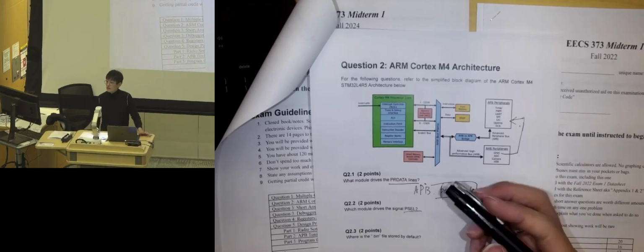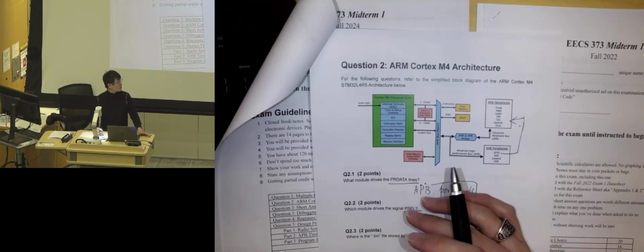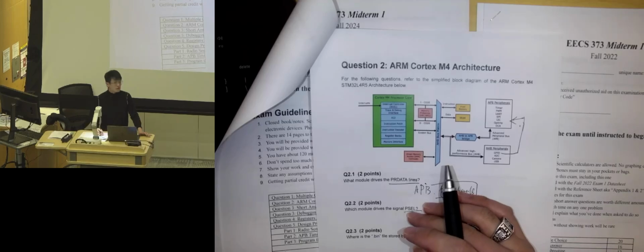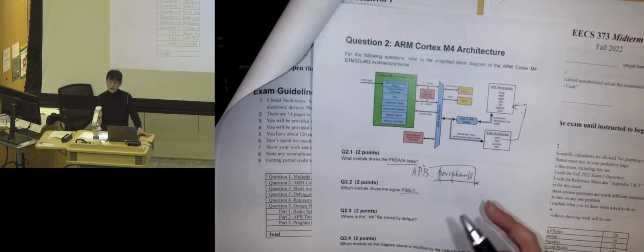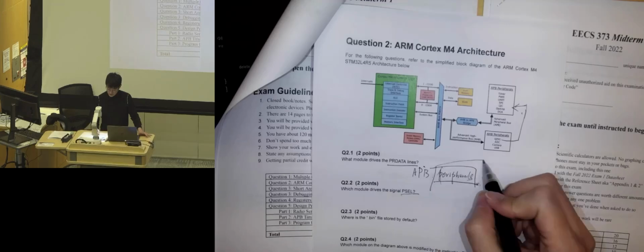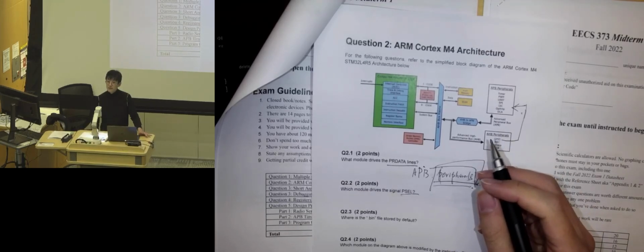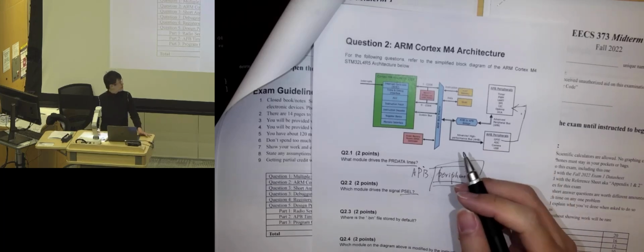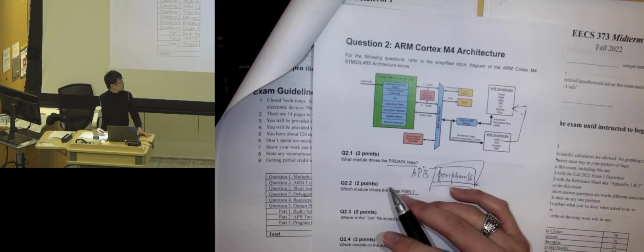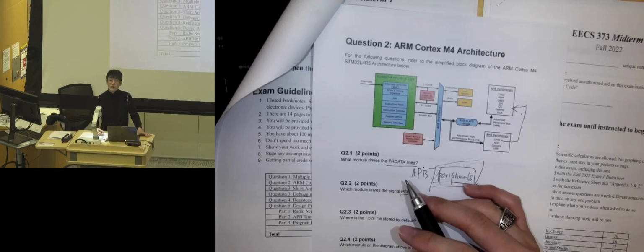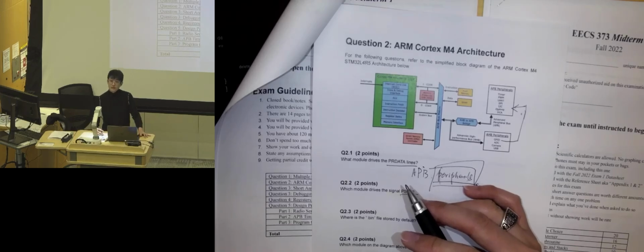So we kind of suggested that. But what's probably really happening is that GPIO is actually looked at as AHB because it has the potential for higher capacity, and you might want more bandwidth transfer over AHB. But in the context of an exam, it's probably always pretty safe, in particular when you're talking about these signals, to refer to the APB.